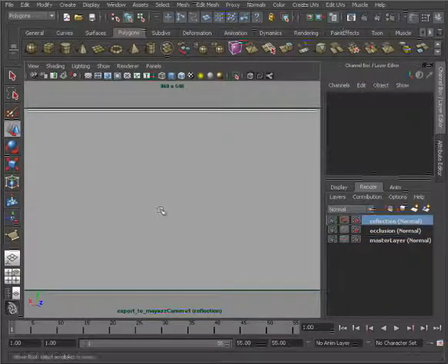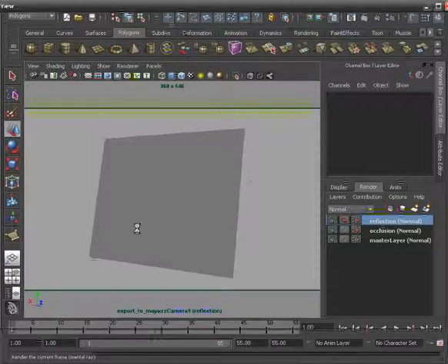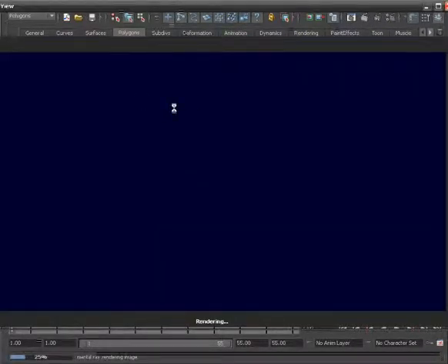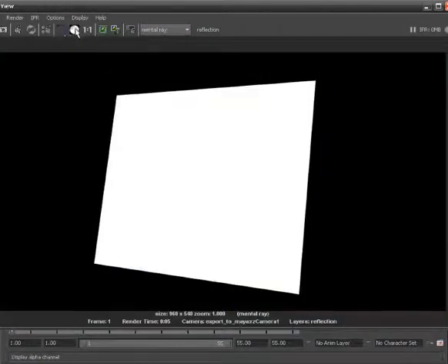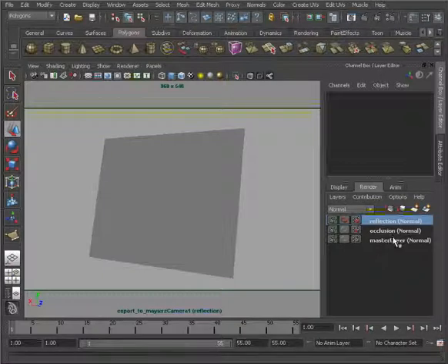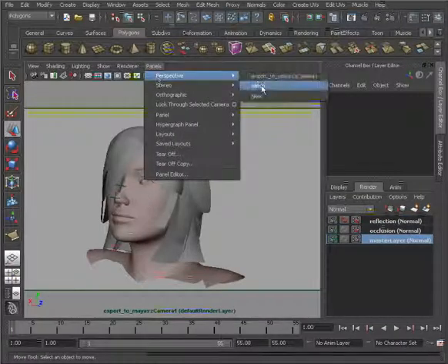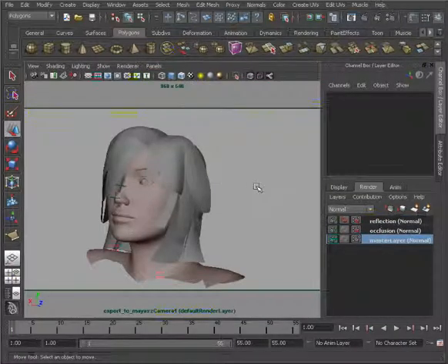And let me see actually in our reflection, if we hit Control-Shift-H to unhide it, if this has an alpha, which it should, and then we can use this alpha as our cutout. Okay, great. So we're now using this layer sort of for dual purposes as a reflection to capture the environment, as well as a way to get an alpha for the cutout or for our camera.